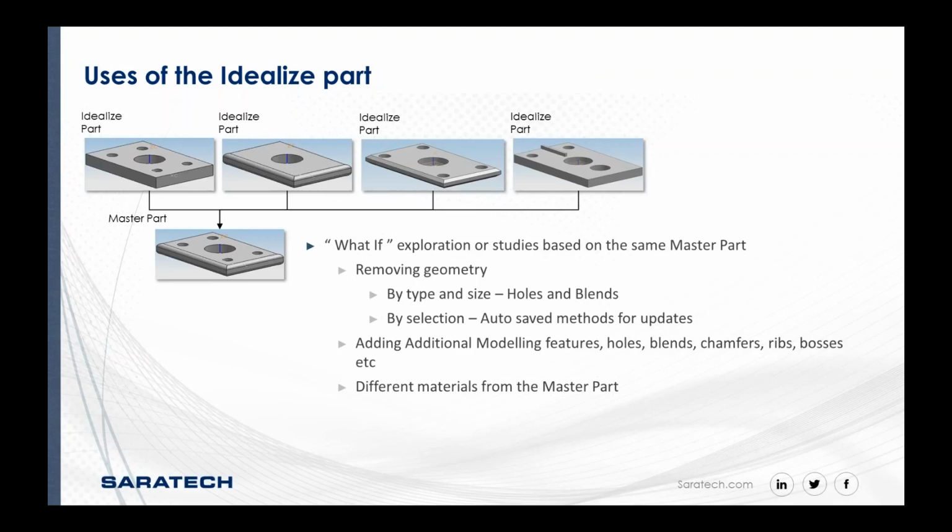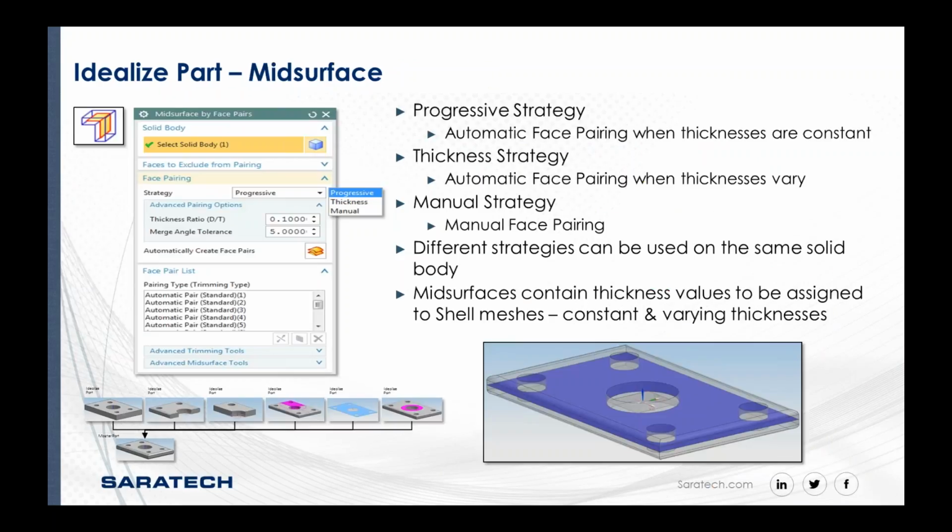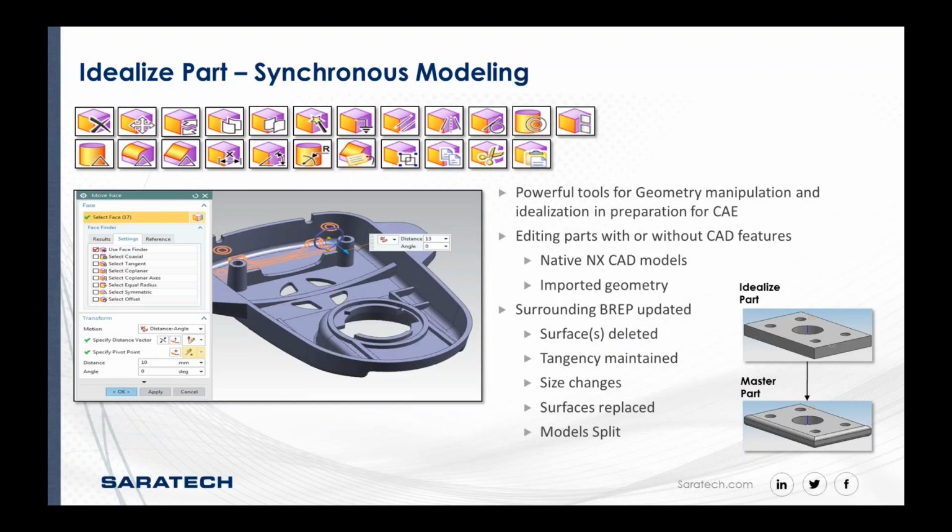So now a couple things that we can do is defeature. Defeature is pretty straightforward. Remove holes, rounds, fillets, things like that. We can create mid-surface representation. A lot of times we're going to want to create mid-surfaces. So creating mid-surfaces is just going to help us get a nice representation of the model without driving element count up. So that's a common FEA procedure to be done.